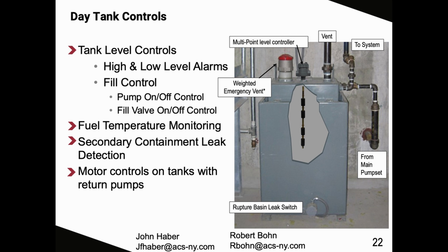Tank basin will include a leak detection switch. Pump supply and overflow connections shall include drop tube connections in the tank to prohibit foaming. FYI, the device with the red cap is the weighted emergency vent. These are illegal for use and installation in New York City.